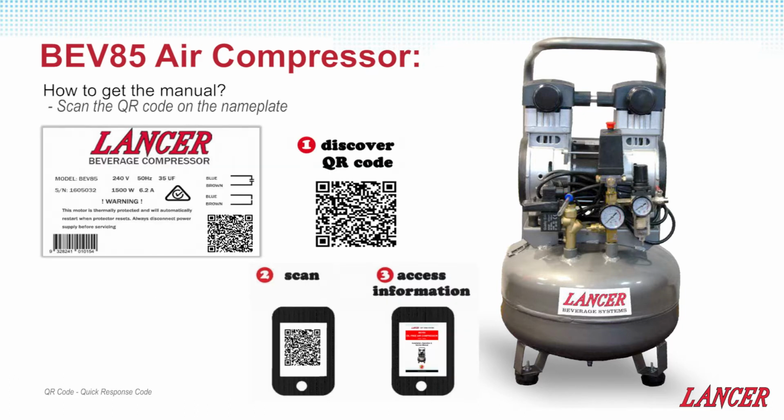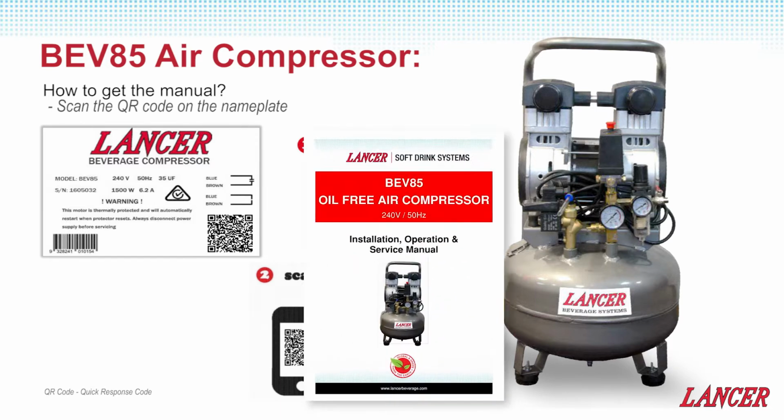If you're unsure of the BEV85 issue, review the manual and its troubleshooting table. If you don't have one, access it by scanning the QR code on the compressor with your smartphone or device that has a QR code reader app.